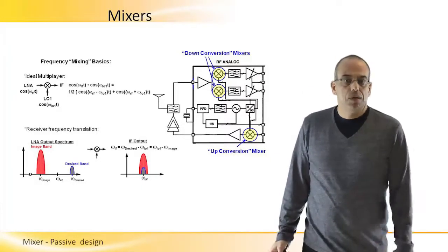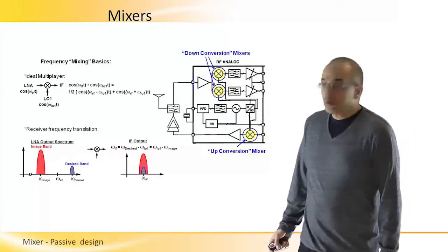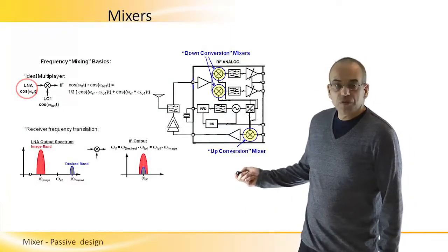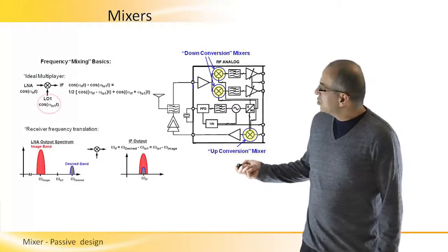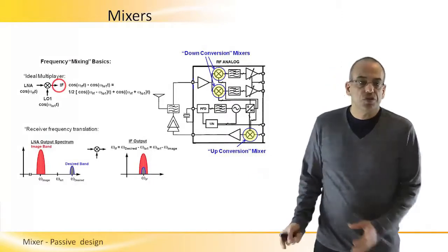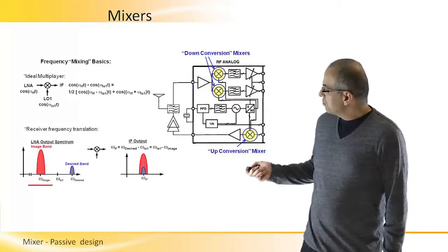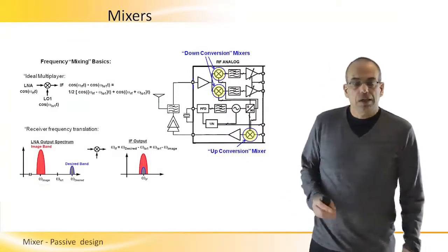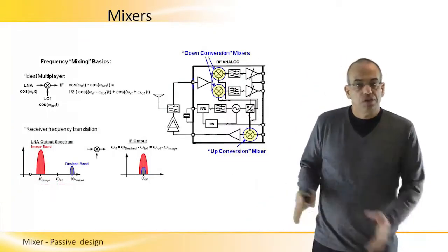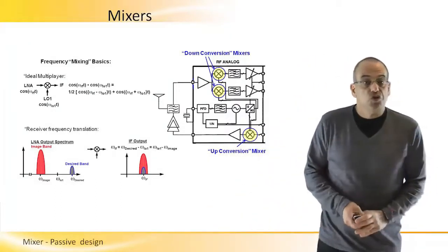And when we talk about the spectral behavior of these frequency converters, we can think about the RF frequency, and next to it we have the LO frequency, and we want to convert it to maybe a lower frequency, but we always need to remember that there's an image frequency that is the same distance from the LO frequency that can be converted into the same IF or intermediate frequency after the conversion.